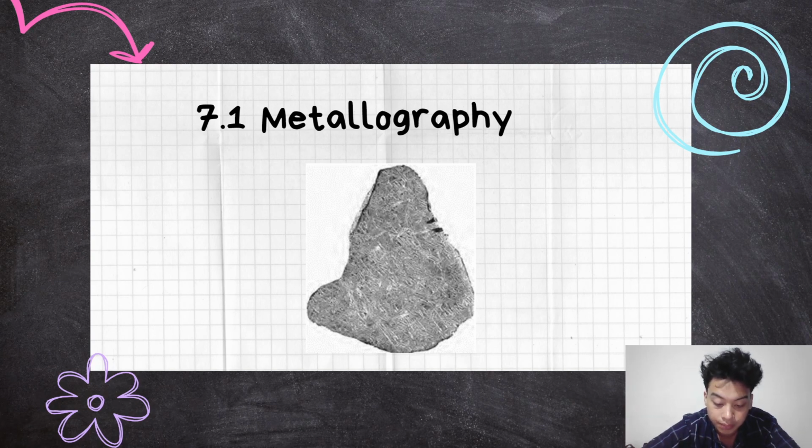Some history. The critical factor in light microscopy of metal is the surface preparation of the specimen. This is the basic insight made by the father of metallography, Henry Clifton Sorby, who in 1863 was the first person to examine properly polished and chemically etched metal samples under the microscope.